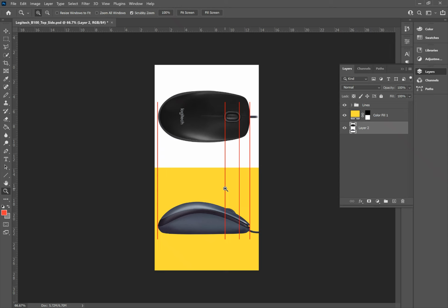Aside from that, one thing to take note of is that as you align your images, make sure that, let's say, the top view takes up a square. I have actually set up 1000 by 1000 pixels for the width and height, so that when I click here, it automatically selects the top image.